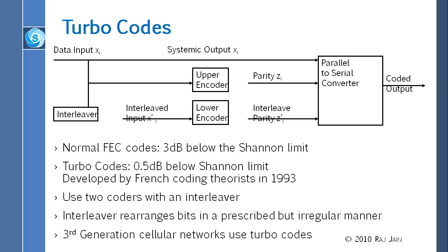So we gave you, I think it was 30 dB, so if the noise was 29.5 dB, what Shannon says, you can get that in a 30 dB scenario with turbo coding. So turbo coding is basically using 2 codes such that before sending to the second coder, you change the order of the bits somehow, randomize the bits and then send it.